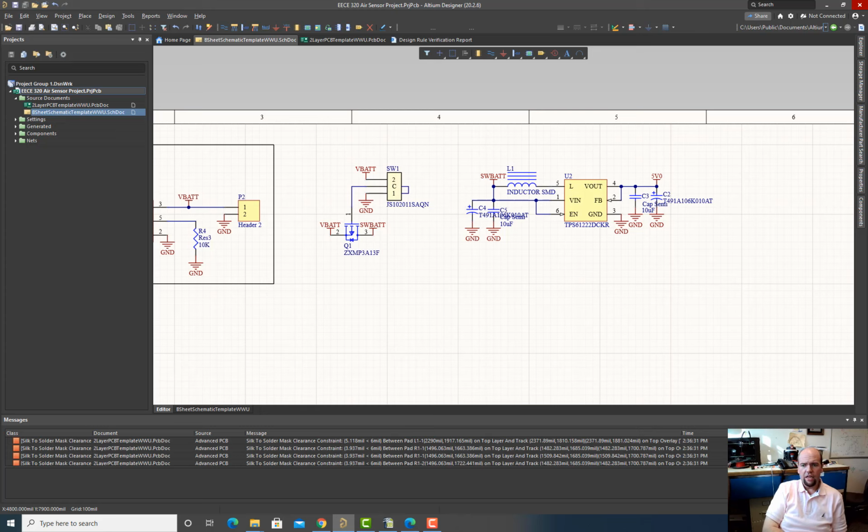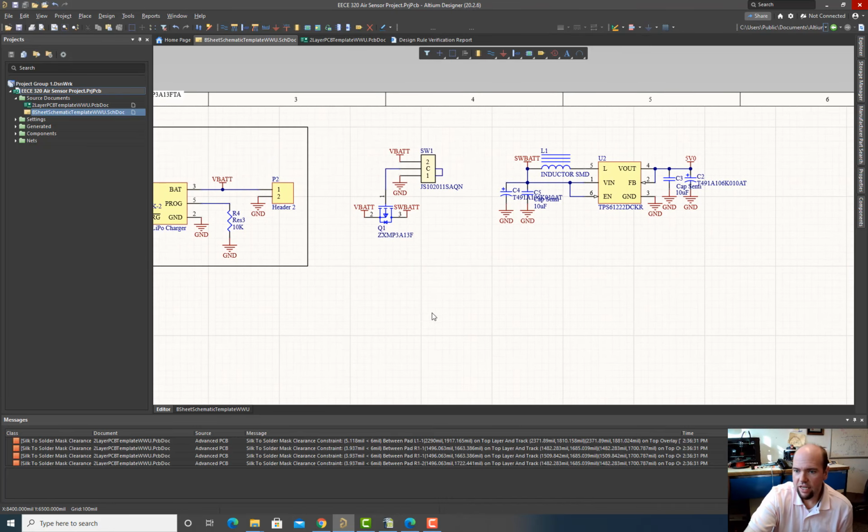Op amps are great for taking real signals from the real world and putting them in a format machines can read, and also taking signals that machines can output and putting them in a format that the world can read. So sometimes it's voltage to current, sometimes it's current to voltage, sometimes it's voltage to voltage. We're doing all these sorts of translations and adaptations of signals, and that's core op amp behavior. I said I was going to break out the sensor, and then I just kept yammering.